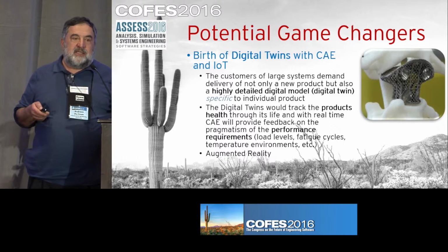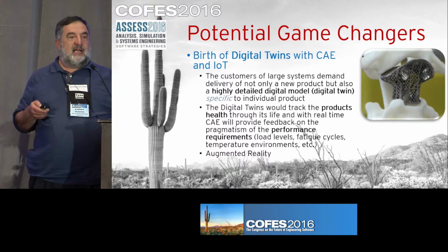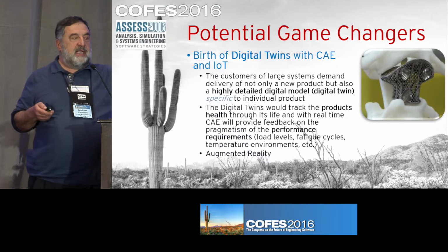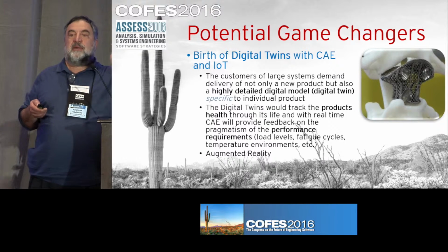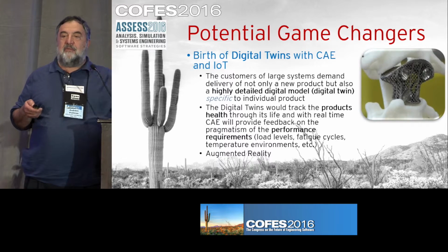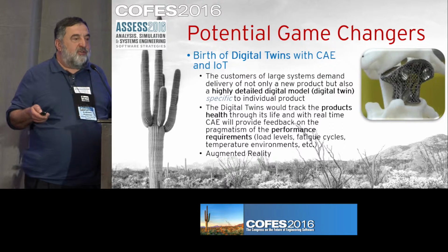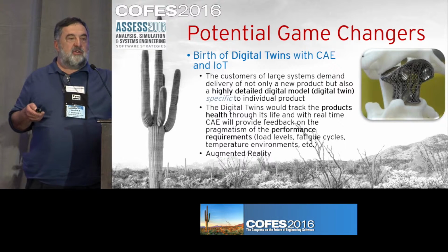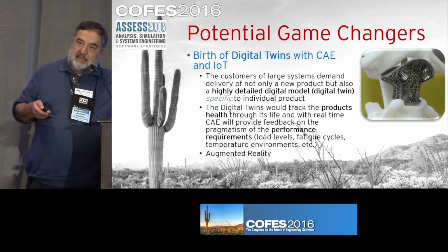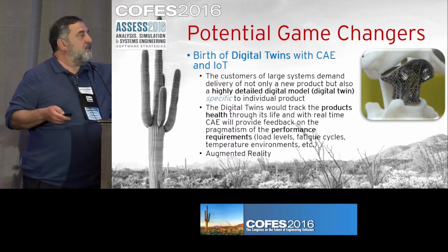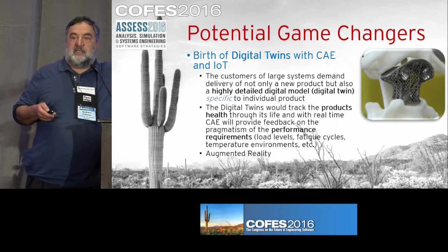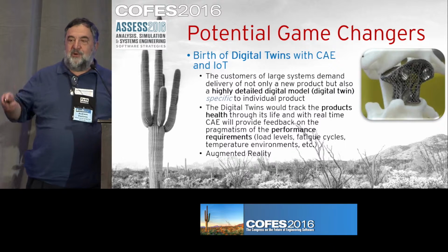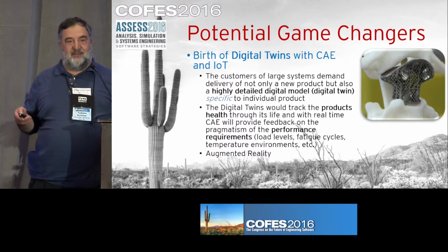Now with digital twins, we don't need the analyst to specify the load. You have the physical twin saying to the digital twin, that's what my load is. So you can have real-time loading, but the simulation software is not built like that. I can say to a Nastran simulation, the load which is applied at that spot and in that direction comes from channel number 5 from the digital twin. They're not built to do real-time CAE all the time, so you can monitor the health of the system.